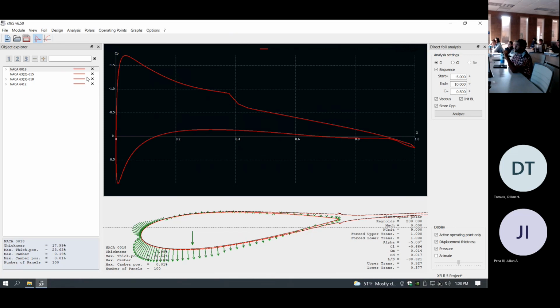Oh, so essentially, and it would help if I had a non-closed airfoil here, but usually when you input an airfoil into XFLR5, the trailing edge, for some of them it autofills, but for a lot of them you will find a little point where the trailing edge won't be completely closed. If you zoom in really closely on the diagram of your airfoil, there will not be a data point connecting the upper and lower surfaces at the trailing edge. There will just be a little gap, the airfoil will essentially be open, and the data you get will effectively be useless.